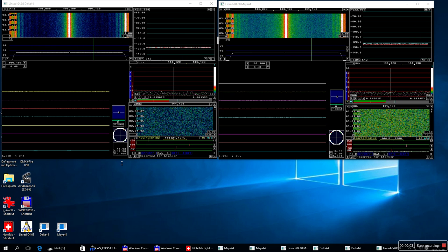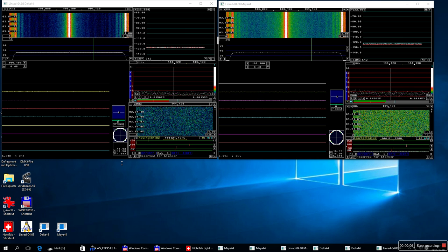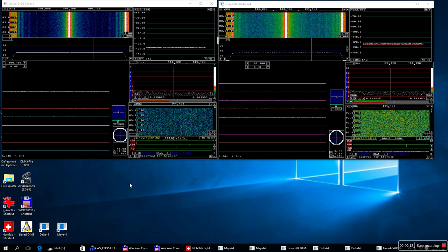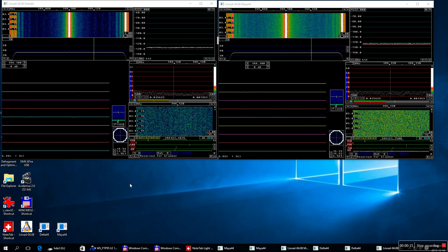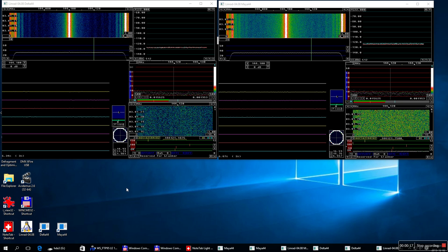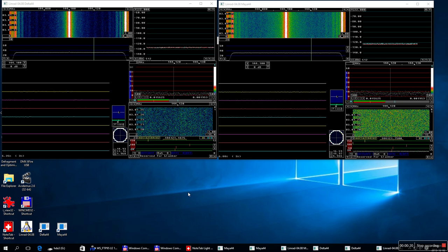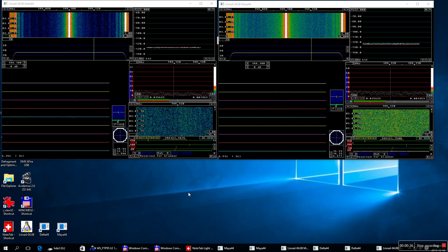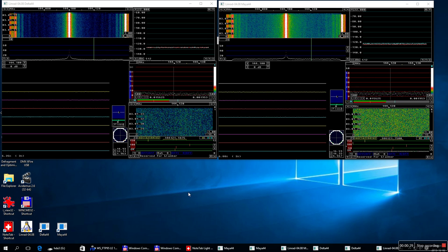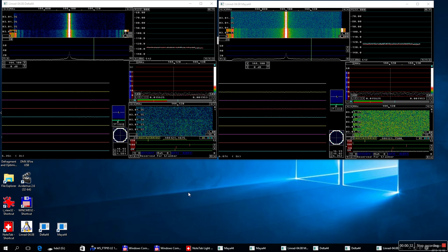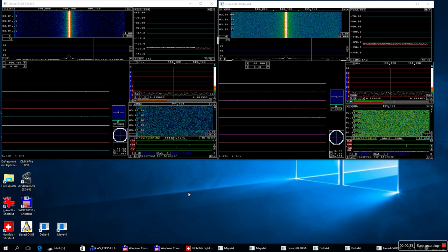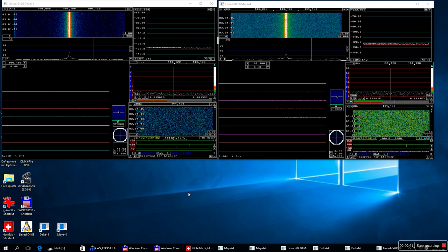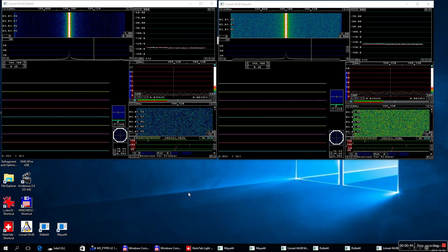While producing this video, I have discovered something interesting. Both sound cards are now running with the noise blanker, the smart noise blanker, enabled. They have been calibrated similarly. And you can see if I disconnect the noise source, that's the pulse generator, that the S meter shows that the difference is very small, a dB or less. And this is a really strong source of noise.